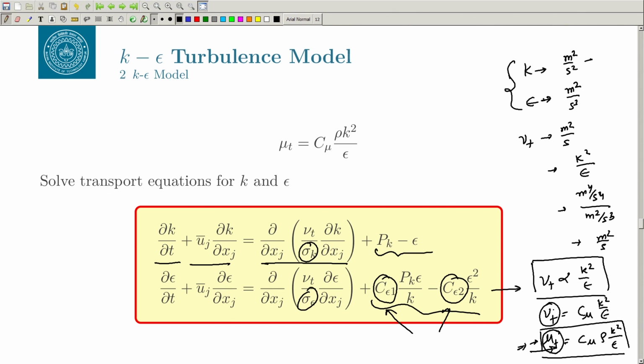Okay, in fact, it is more stable, right? Remember the argument that you had made about this Lax-Friedrich scheme, and we said that it is highly dissipative, right? Because it has got a high numerical viscosity. So, in effect, if you talk about the eddy viscosity, we are multiplying. So, earlier, let us say you had mu del u bar by del y.